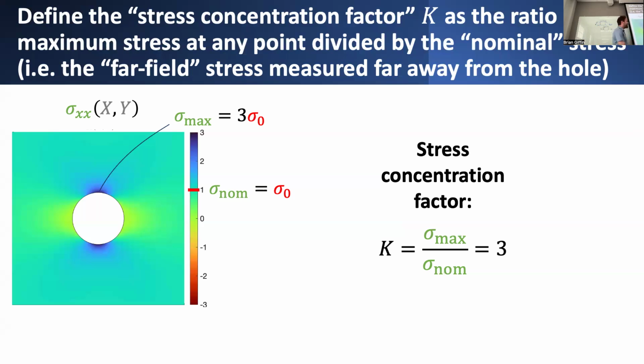For that, you really just need to know, what's the maximum stress that would occur if I were to drill this hole? And to do that, all you need to know is, if I can figure out what's the average stress that would otherwise occur in this plate if there was no hole, and if I were to go through the trouble of finding these elasticity solutions, I could figure out what this maximum stress is. And then I could just figure out in a relative sense how much bigger that maximum stress would be relative to the average stress. And that's encapsulated precisely through this stress concentration factor.